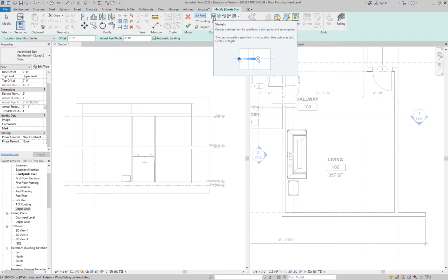If you know that you don't want to do the move command, before you start, draw in your reference plane. So pretend our wall is here again. Should have used a different color. But let's say you measure, if you know your stairs are 3 feet, you might put in a 3 foot reference plane here, so that you know where to click to start this one, okay? If you want a bigger landing, then you can make that 4 feet or whatever size.